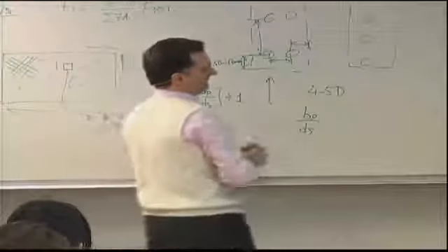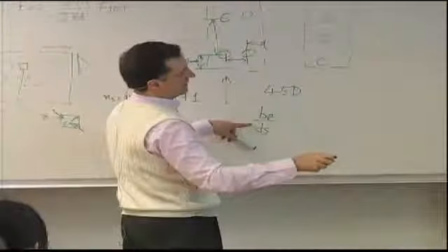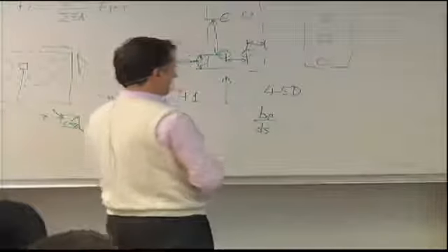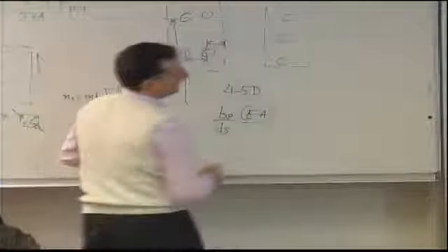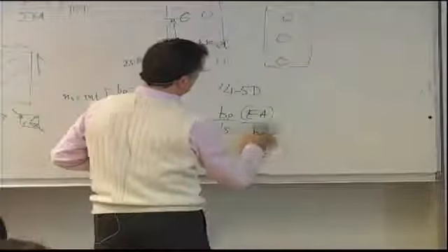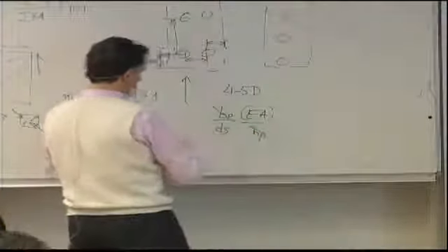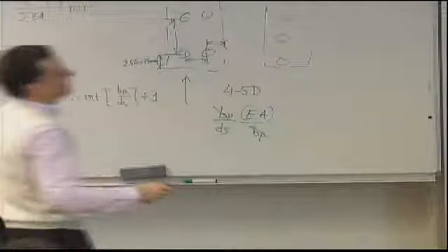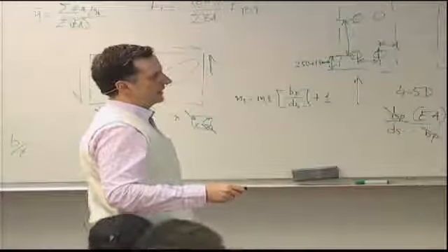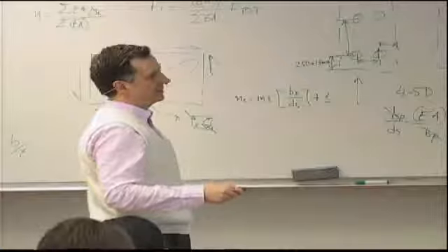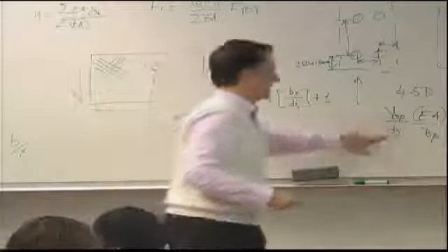I multiply the NS by the A for a single stiffener, which is EA divided by BP again. So these will cancel, and I get what's at the top right as the contribution to the A11 term for the skin and stiffeners: A11 of the skin plus this term, which is the EA divided by the spacing of the stiffeners. We will continue next Friday.